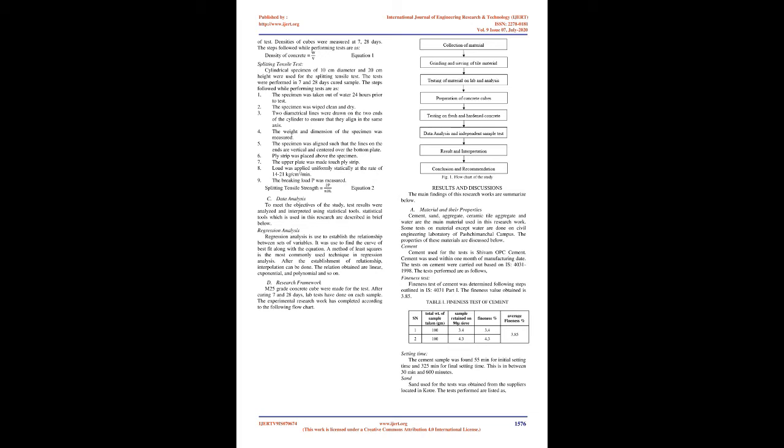On the study of ceramic tile waste used in concrete as a replacement for natural coarse aggregate with 0%, 10%, 20%, and 30% of the substitution and M20 grade concrete. The concrete molds were cast and tested for compressive strength and split tensile strength after a curing period of 3, 7, and 28 days. The results indicate that the maximum compressive strength is obtained for the 30% replacement of ceramic tile aggregate with natural coarse aggregate.